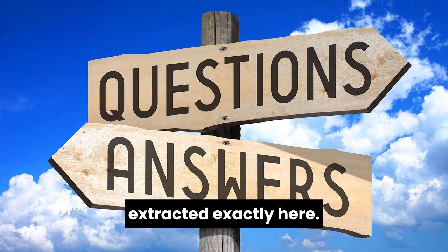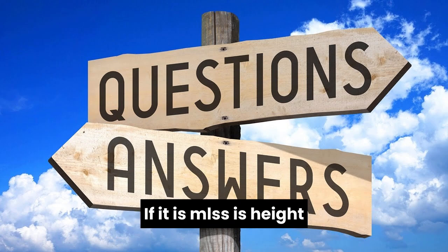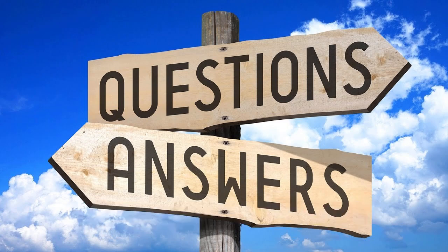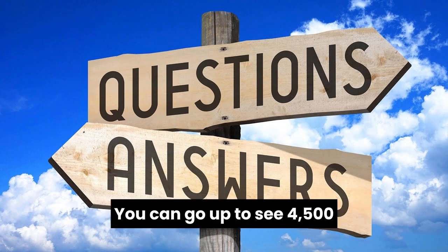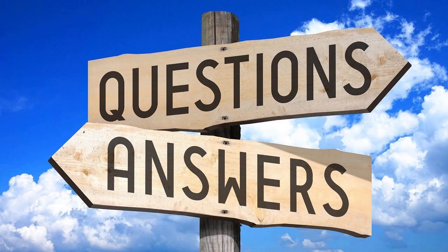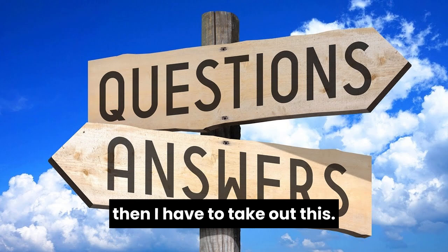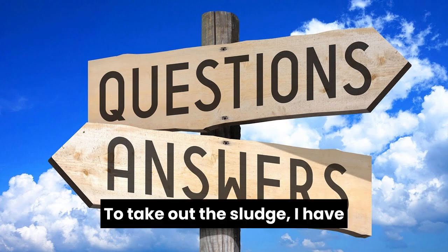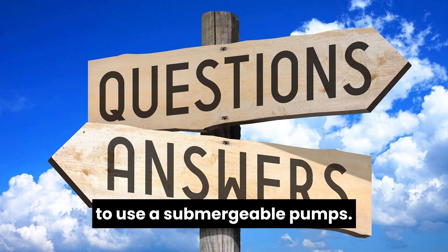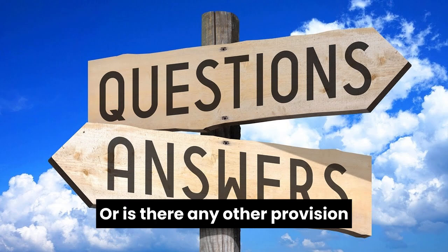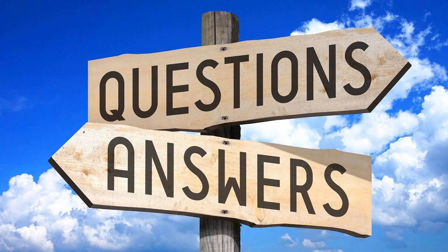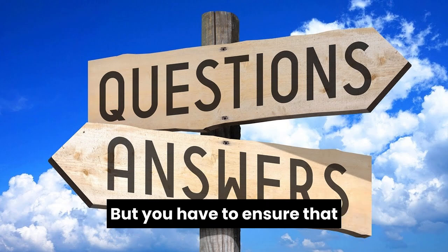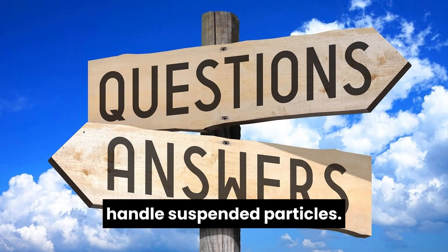After extracting this, if the MLSS is high, normally we are keeping MLSS at 3,500. You can go up to 4,500 in your SBR tank. If it is more than that, then I have to take out the sludge. To take out the sludge, do I have to use submersible pumps, or can any other provision be accommodated? You can use submersible pumps, you can use airlift pumps, you can also use centrifugal pumps, but you have to ensure that the centrifugal pump can handle suspended particles.